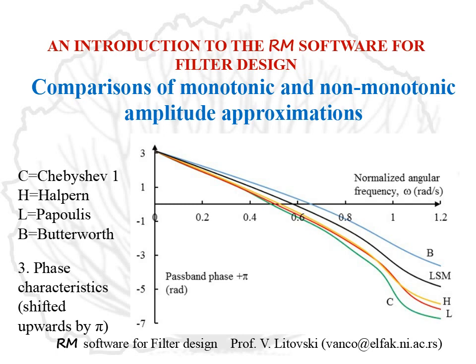In general, it is not easy to capture the properties of the filter by simply looking at the phase characteristic, but nevertheless one can see that the Butterworth filters have a much more linear characteristic than any other, and that the Chebyshev filters have the most nonlinear phase characteristic.